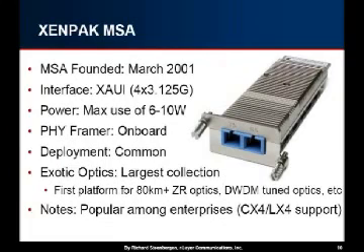The next standard, and probably one of the most, if not the most popular or second most popular, is the XENPAK. So this was an MSA founded in 2001. It features a XAUI interface, which is 4 channels of 3 gig talking to the system. It has a max power use of 6 to 10 watts. And when I say max power use, what I mean is there's different power classes. We'll talk more about that later. But in terms of maximum draw, those are the classes. So you are looking at a maximum power use of between 6 to 10 watts. The framer is on board. I'll go into more detail on this. Just a quick overview.